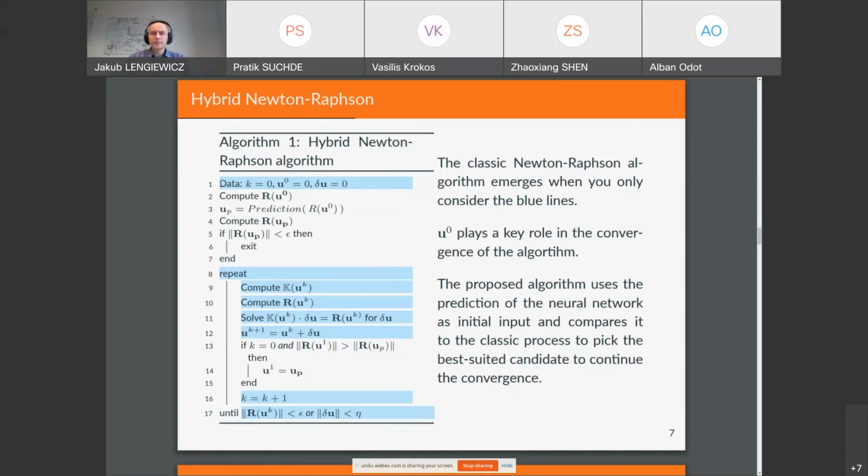Nice. So if we consider only the first line, we set the initial properties of the system to have a null displacement. So we work at the rest shape. And then we compute the Jacobian, the tangent stiffness matrix, sorry. The residual forces, we solve the equation for the displacement. And then we iteratively modify the position of the object, in our case the beam, but it works on anything.